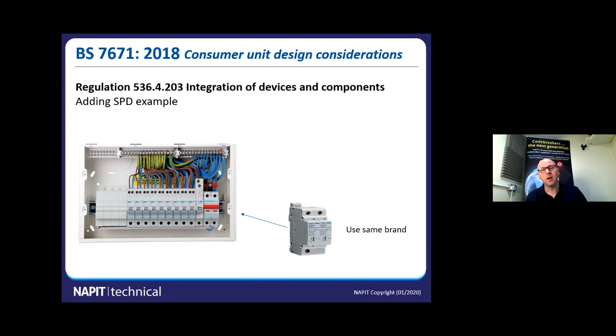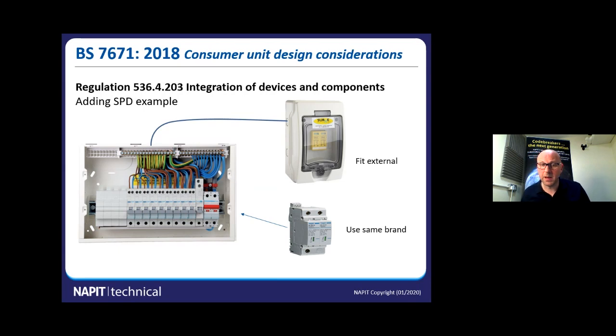That's great. If you want to use a different brand for whatever reason, it may be that you prefer that brand, it may be that there's other SPDs within the installation and you want to match the brand. That's all important stuff, and we'll be talking about that on a future webinar. Then fit it external. It can be sat there external to it, no problems. Now we will explain when we cover SPDs at a later date that there is a maximum distance of how you run the tails, and it's quite short. So make sure that if you're going to sit it next to or on top of a consumer unit, you put it right close to it so that you can keep those cables to a minimum. And like I say, we're going to go into that further later on.